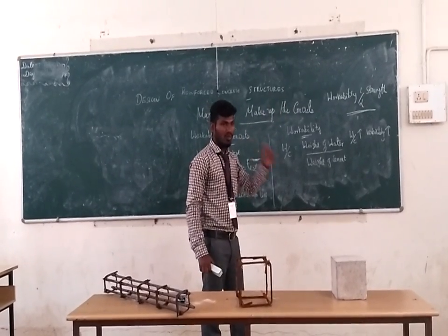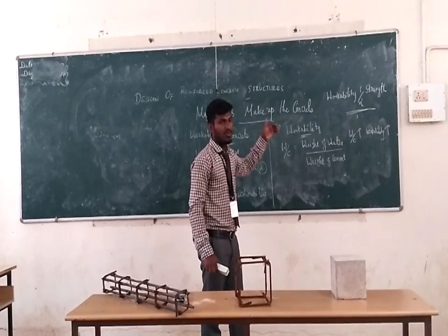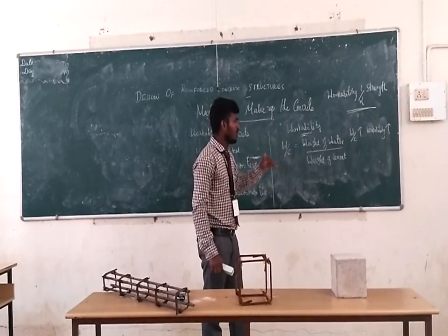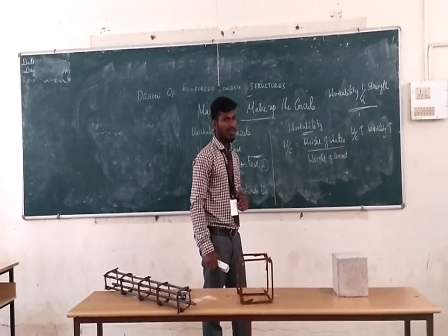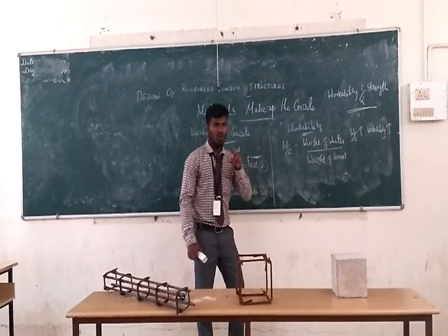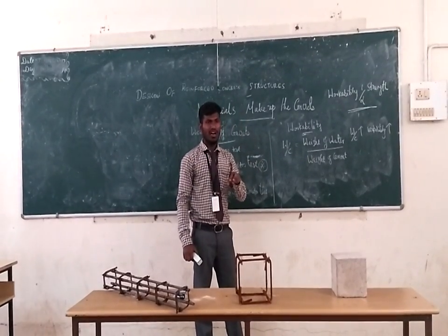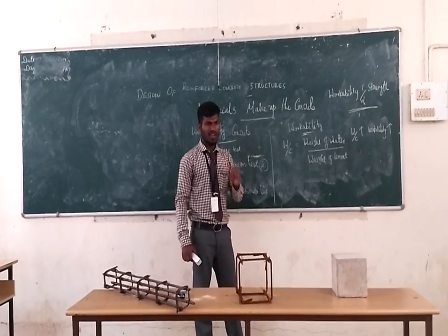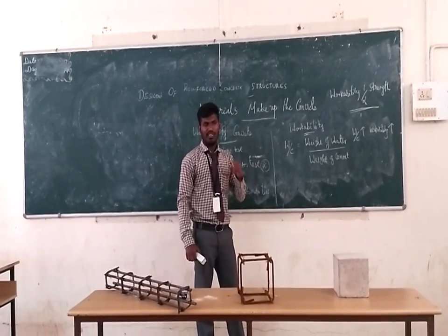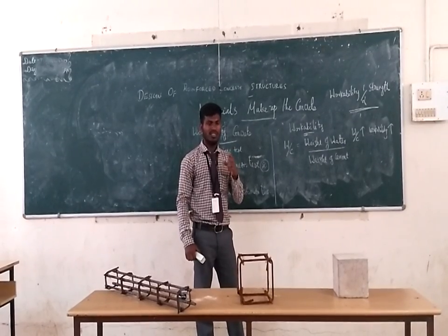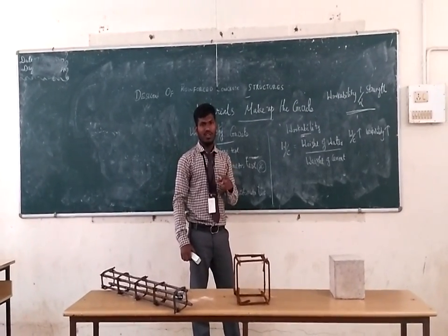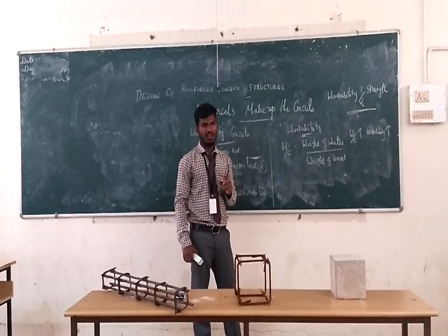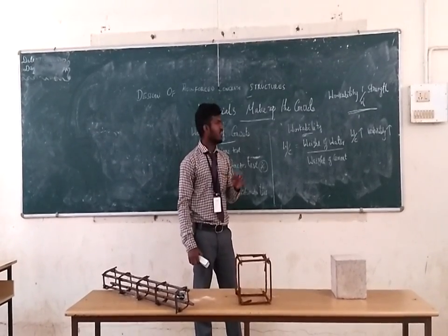If we need more strength, the workability has to be lower. But if we maintain lower workability, the concrete will be stiff and dry and hard to mix. It resists compaction, so honeycombs will form in the concrete, which also affects the strength of concrete.